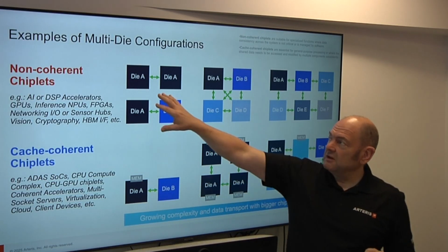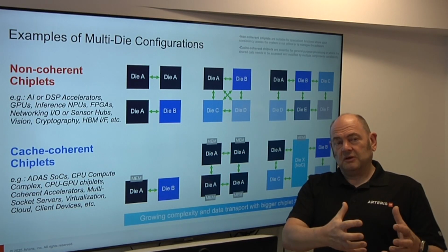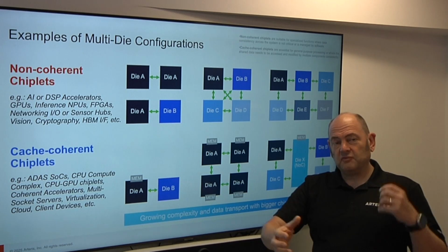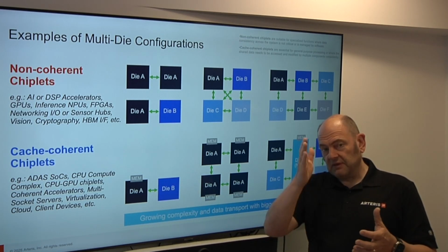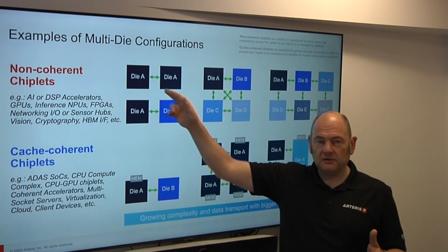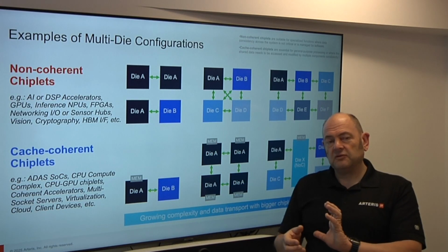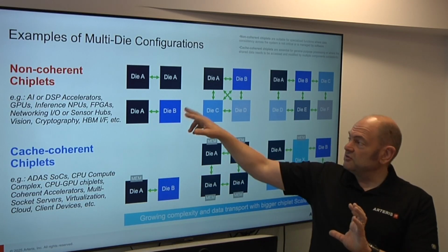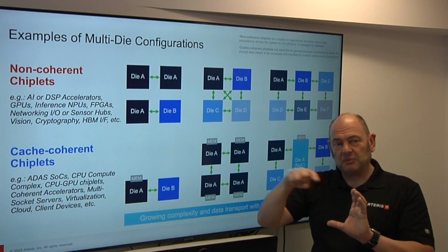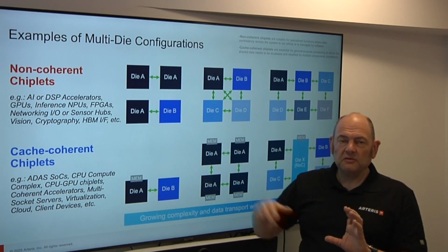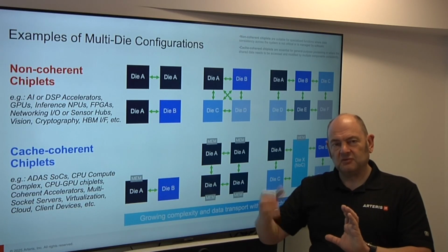So in some ways we have conventionality where you execute your normal design flow, your architecture, your implementation, and your validation. And then you've got that multi-die interface that you have to validate, and the flow will also execute in the same way if it's a new die. If it's the same die and you're plugging back to back, then the validation happens between the two dies. If it's a new die that you're adding in, of course, that will have its own flow. It will have architecture, implementation, validation.